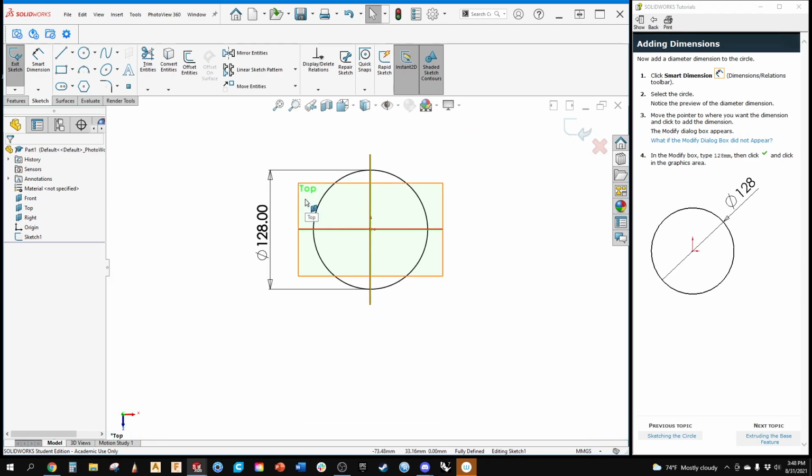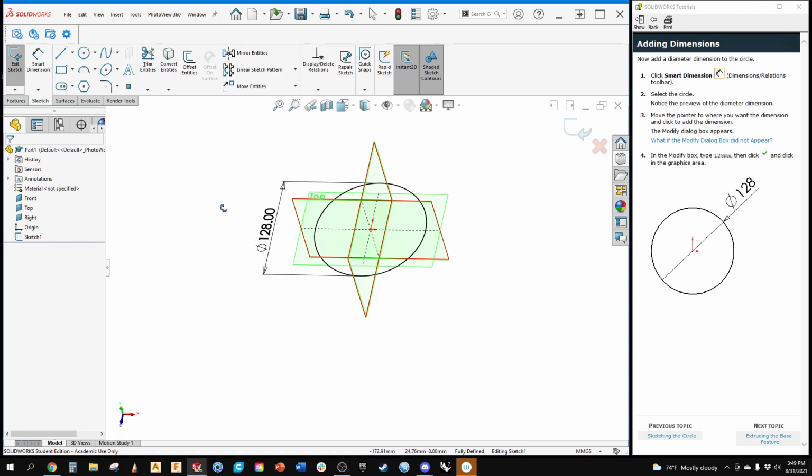So now what's visually represented is more accurate, but depending on your computer and your graphics card, it may slow down your screen. So we kind of talked about that before. Even if I'm working on a massive assembly, let's think about a piece of large medical equipment that has absolutely everything in it: bolts, nuts, circuit boards, and all that. If my machine bogs down, that's the first thing I do is to turn that down. So, whole lot of talking I just did.